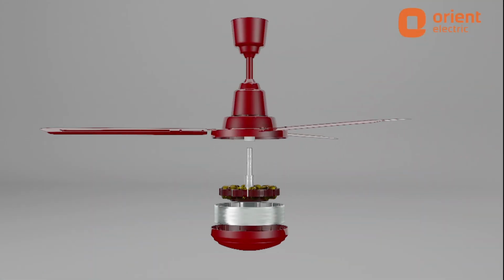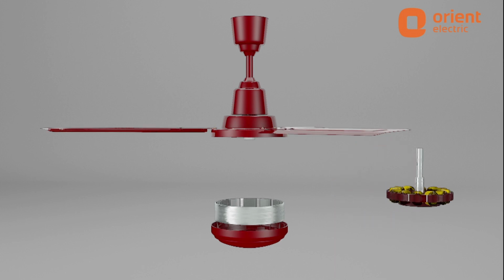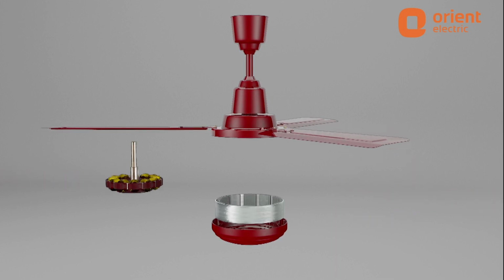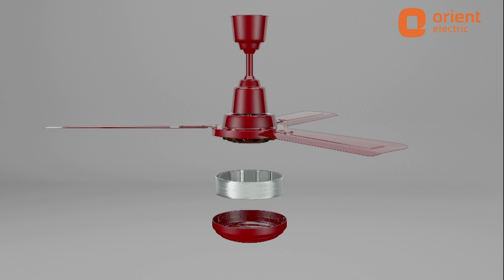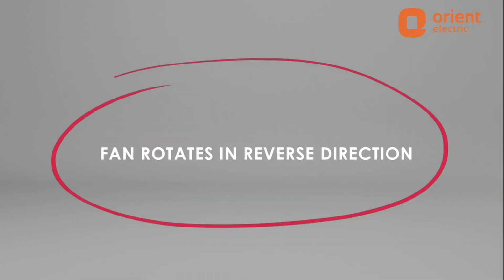Burnt or open circuit fan motor winding can also be the culprit. Therefore, you should check continuity of the fan motor and connections by multimeter or series lamp and replace it in case of any defect. Fan rotates in reverse direction.